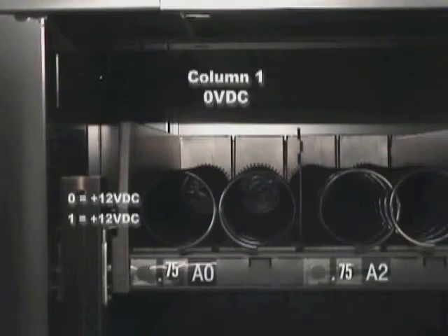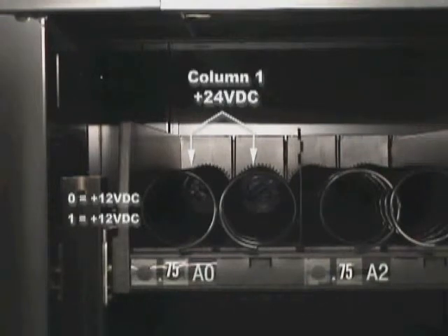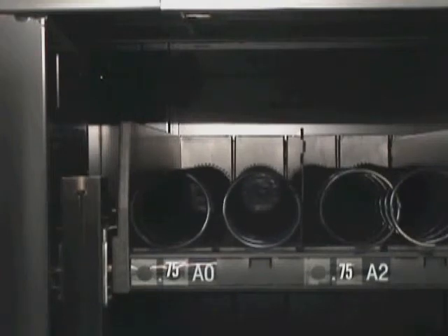For example, to run the motor for the A0 selection, column 1 is energized, putting plus 24 volts DC to all 0 and 1 selections. Row A0 even goes low, putting DC ground at even motors A0 through A4. Since motor A0 is the only one having both plus 24 volts DC and ground applied, motor A0 runs. The entire motor matrix is designed such that only one motor can possibly run when any one pair of row and column lines is active.